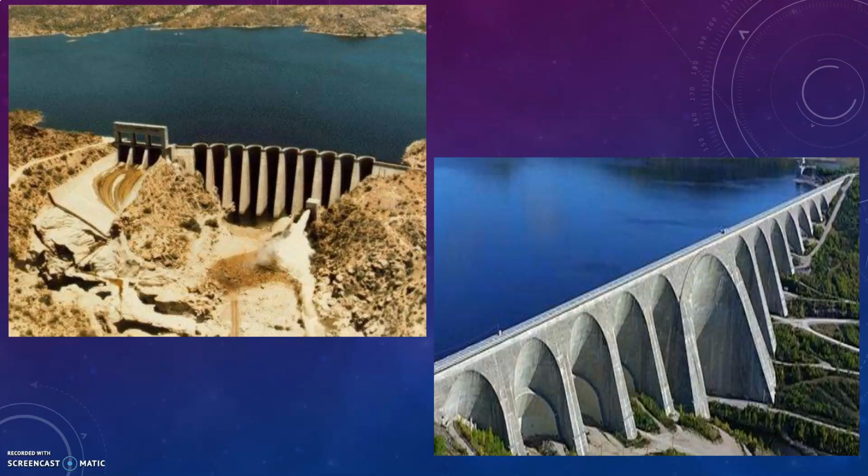Access is possible to the back of the upstream face and to foundation between buttresses for periodic inspection and for subsequent grouting and drilling of pressure relief holes if required. So, the most efficient use of strength of concrete leads to the economy in quantity required, though the financial economy will not necessarily be directly proportional to the quantity of concrete saved. So these are some of the advantages of buttress dam.